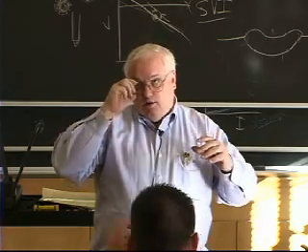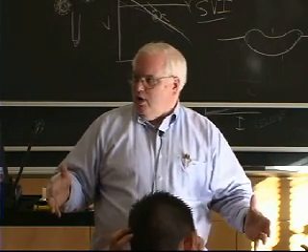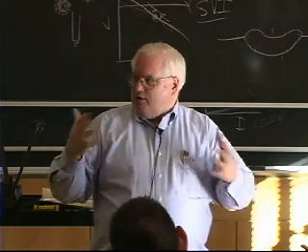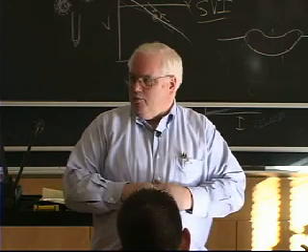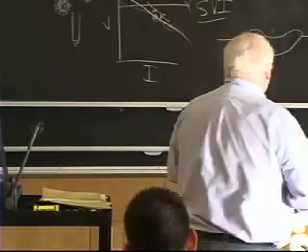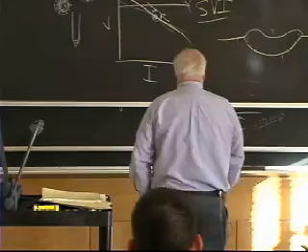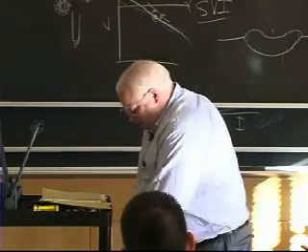And so if you see someone welding outdoors and they have curtains around the welding, it's not just to protect other people from the radiation. It's to protect the weld from the wind blowing by and blowing the arc away, because you can get a defect. Now there are other things that can blow the arc away. One's magnetic arc blow.